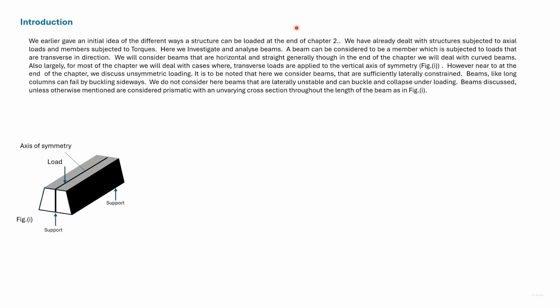In the case of torque, the torsion formula related the internal torque to the stresses acting on the section. In the case of a beam subjected to load on the axis of symmetry, we'll find out a relation between the internal moment and the stresses acting on a perpendicular section.